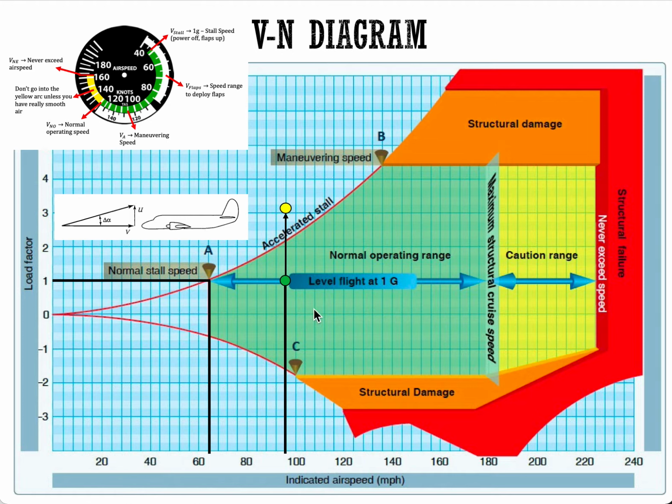So say you're cruising along, you enter into a cumulus cloud where you have really high turbulent winds. Suddenly, there's a thermal coming, or a gust coming perpendicular to the wind, or in any direction, that may increase the load factor on the airplane from say 1G to about 3G, in a worst case scenario. If that happens, the airplane actually stalls, and that may cause the airplane to pitch nose down, and you'll be able to recover. Which is good. Again, it's better to stall the airplane than structurally damage the aircraft.